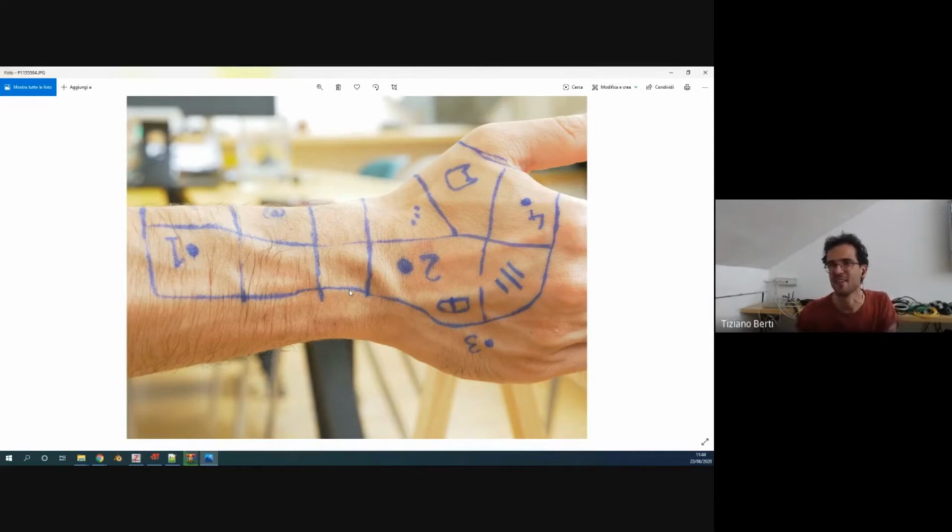The software never gives you the scale of the object, so we always need to measure something in reality before getting the photos, or just after, before removing the markers. This is another thing I forgot to say before. If you don't do that, your data set will be unusable.